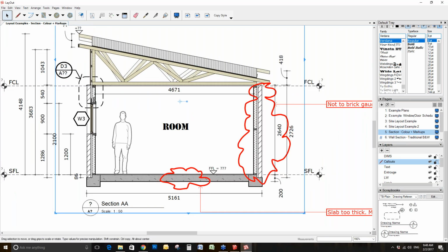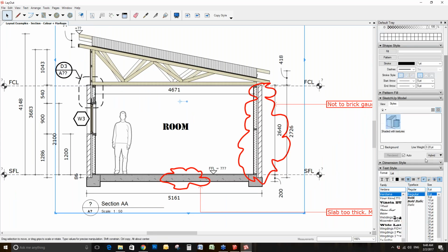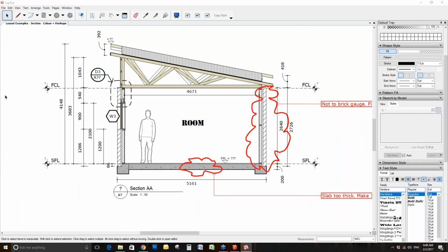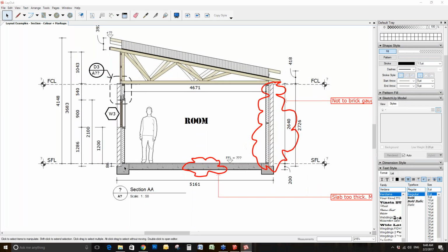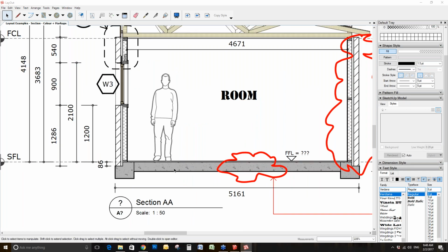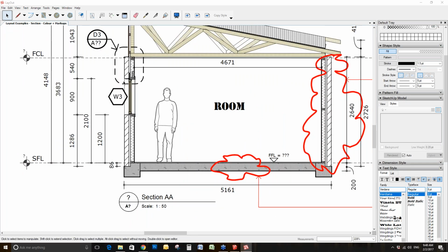I've brought it in there. If I go into this particular drawing, you'll see that I've set the line weight to this style and it's on a hybrid. Again, I can manipulate it if I want to. You can't use vector if you want to be able to show the PlusSpec smart hatching. It has to be on the hybrid or in raster. And it also can't be hidden line. Hidden line actually hides the PlusSpec hatching.